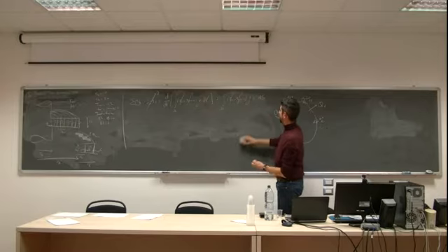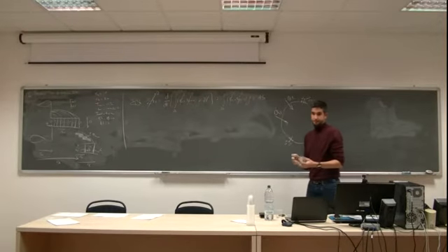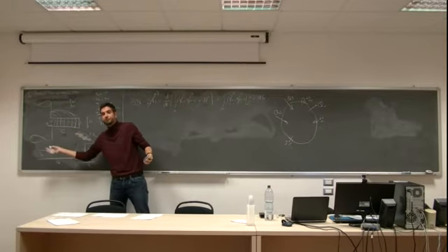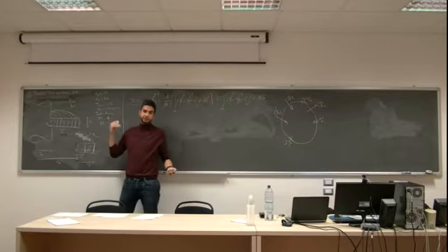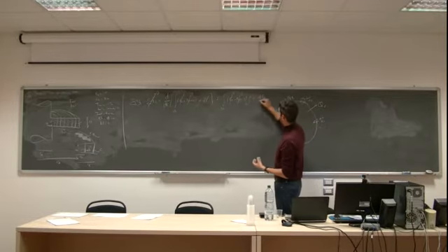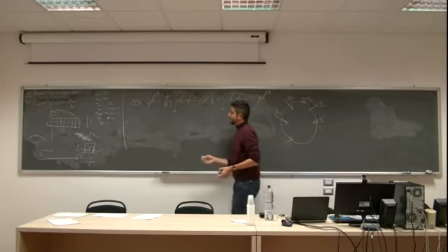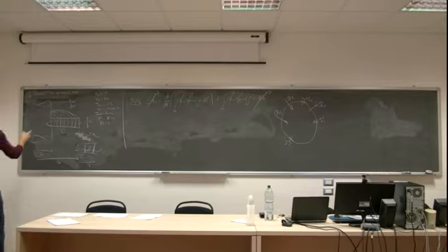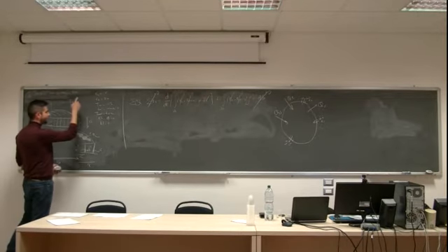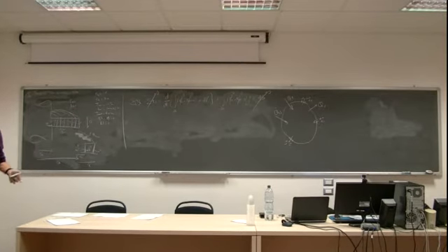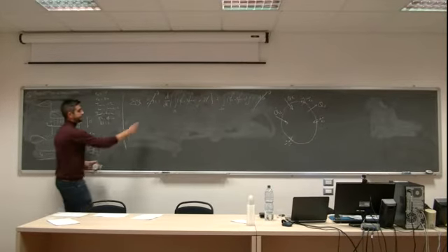Now, in the case that we are doing, we don't have any exchange of mass in my fin, right? There is no mass going to the fin or moving outside the fin. So in this way, there is no dS, there is no surface of mass exchange. So that is 0. For that, everything is constant in temperatures. Wall temperature is always 70. Air temperature is always 25. Heat transfer coefficient is always 10. So this is a steady state problem. There is no evolution in time. That means that this derivative is 0.